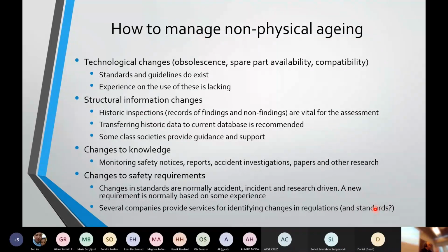But of course, it might be problematic if we need to do repairs on something that is welded with an old technology and with old steel, and we are introducing new steel. You could have these kinds of compatibility problems, where the old structure starts corroding heavily because of the difference in materials and so on. So it's not irrelevant, but it's often not as much a problem for structural engineers as it is for mechanical engineers.